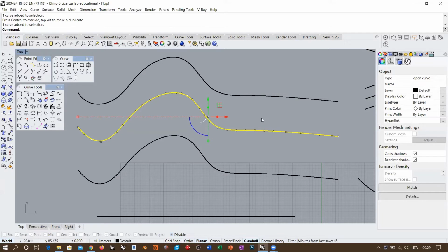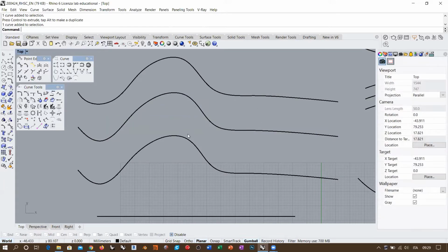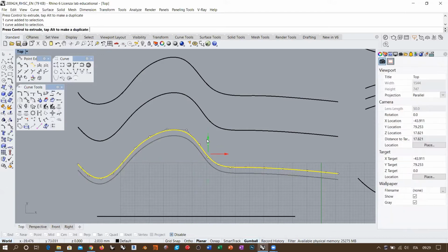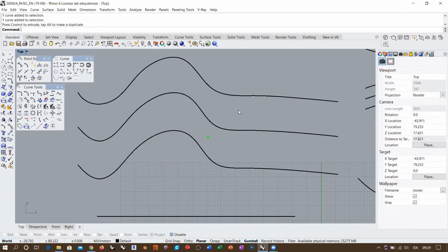Okay, so there are two ways basically. One, which I normally say in a simplified way, is that the rebuild non-uniform is based on curvature. So if you want to approximate a curve which has an irregular behavior of curvature along the path, then you might want to use the non-uniform if you want a more precise rebuild of the curve.